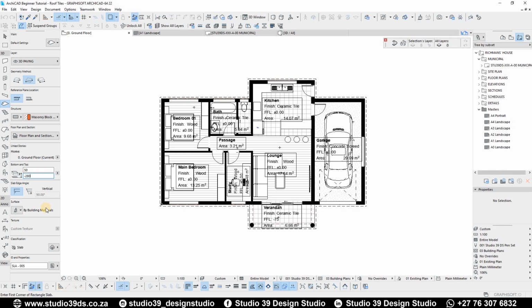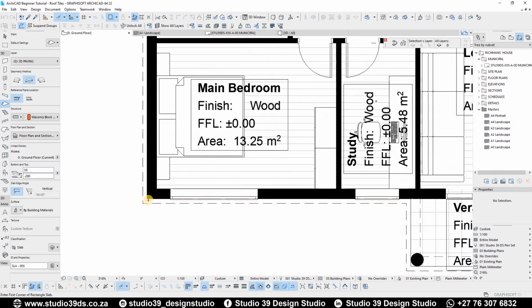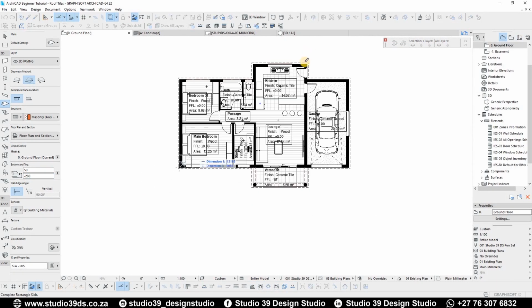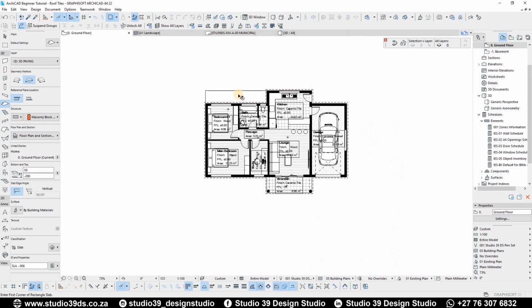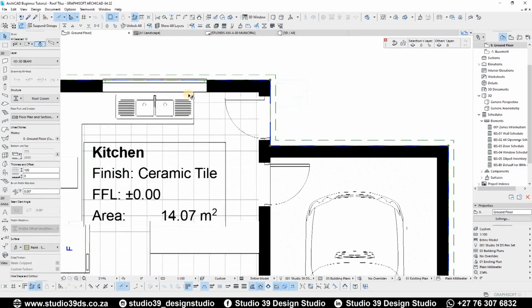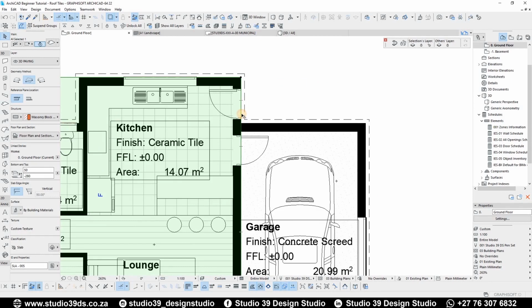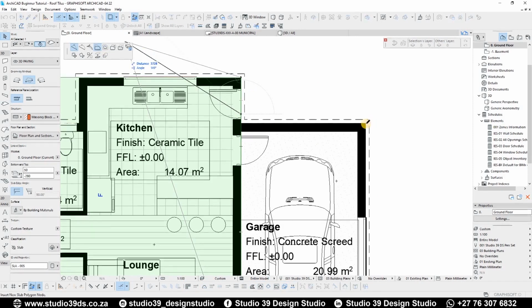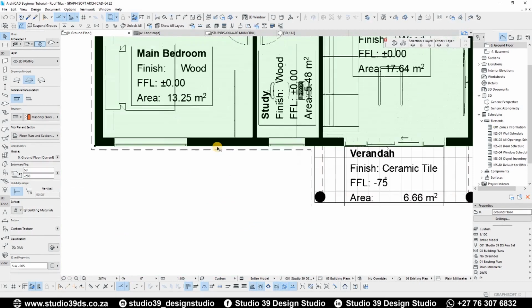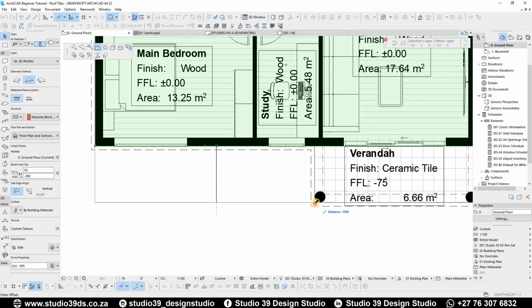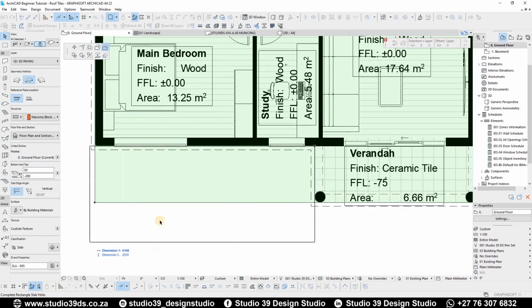It can be not minus 28, but minus 280, or 28 centimeters. What I'm going to do is go ahead and draw it up from this point to that point, and then add to the polyline offset. I'm going to offset it from that point to that point, and then once again from that point to that point, and then subtract from the polyline that point like that.